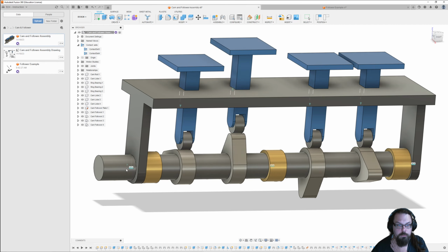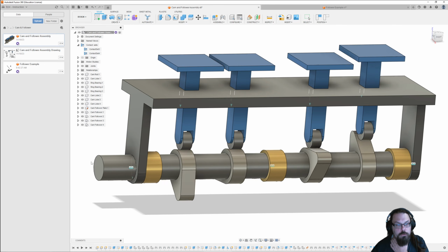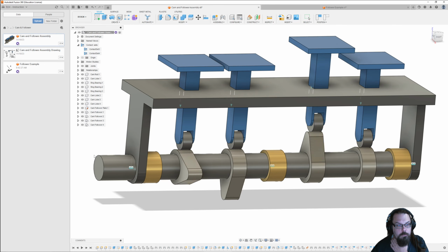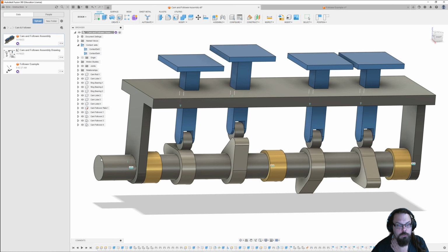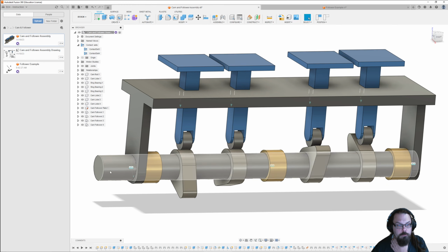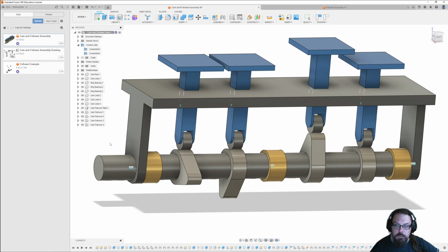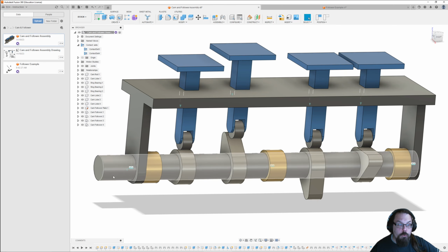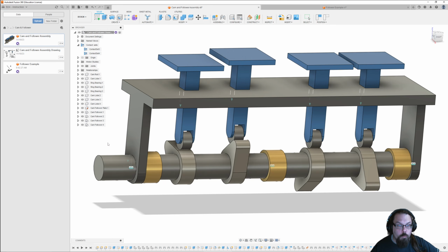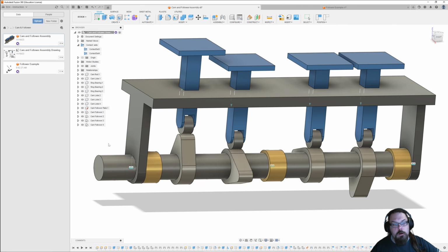I will have to do more research, but in theory, it should be solving that problem. But you'll notice that as I added these contact sets, the smoothness of this animation went down pretty dramatically, and that is because calculating contact sets takes up a lot of CPU power, or it's more processing intensive to work with contact sets. So if you are trying to simulate motion and those types of things, having the minimal amount of contact sets necessary can save you processing and resources time.